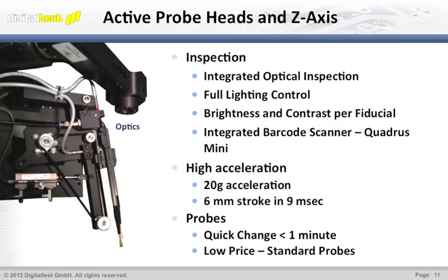Also, as standard within the system, we provide AOI. This will allow us to look at resistors, capacitors, presence, absence, look at the part markings, look at rotation of components.